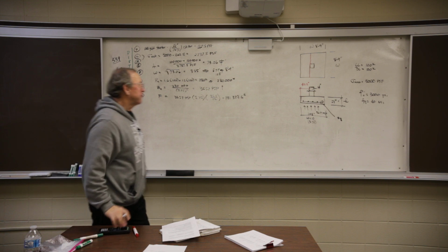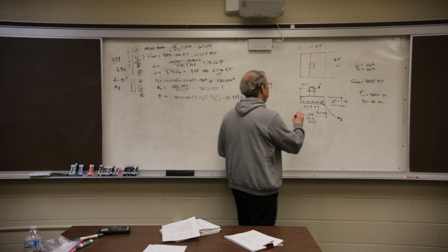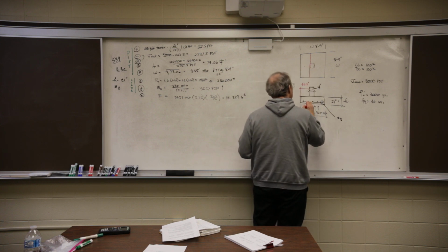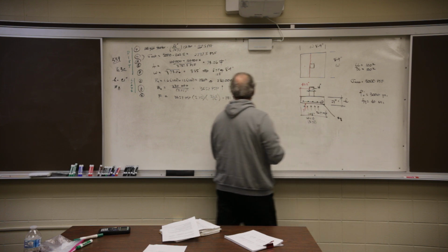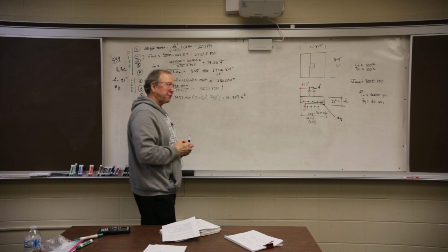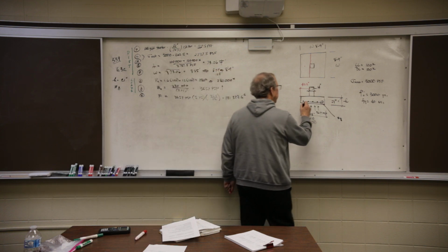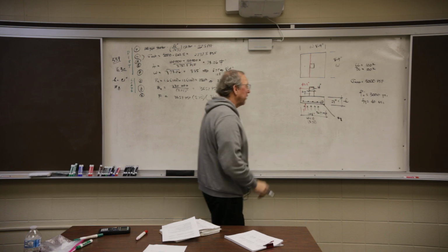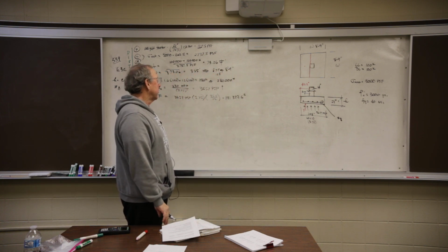So I've got a force pushing right here. That's the resultant, right in the middle. And that's the force of 121,000 pounds. Where's it acting? Here's the arm. The arm is just the center of the section. In a rectangular section, that's in the center.